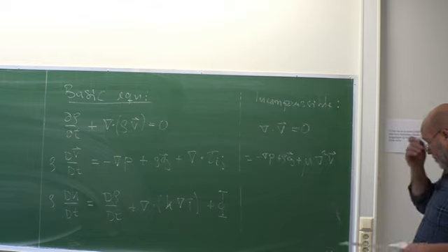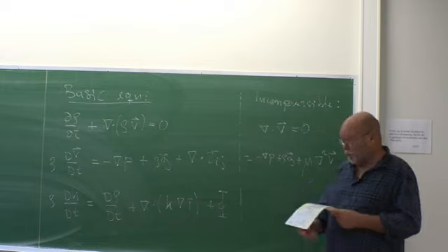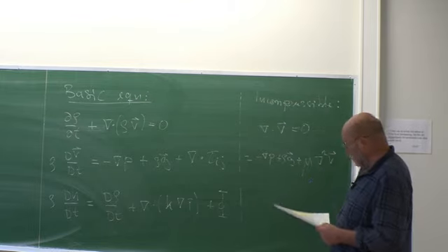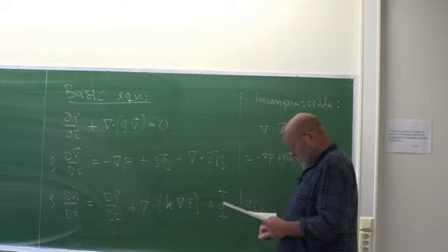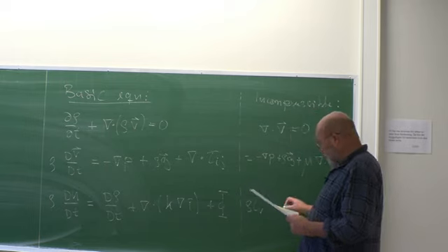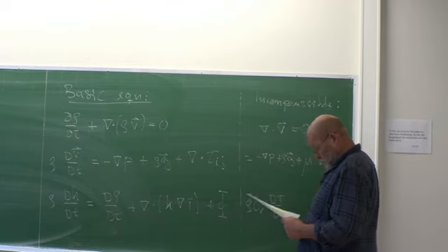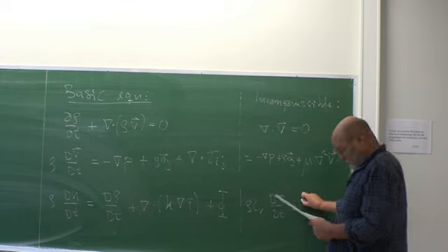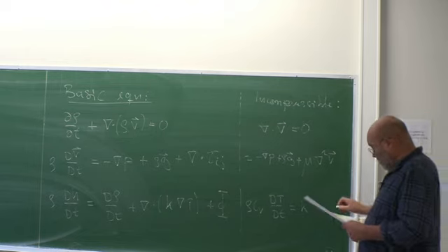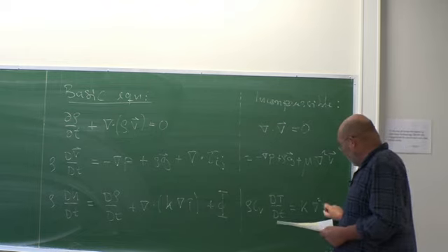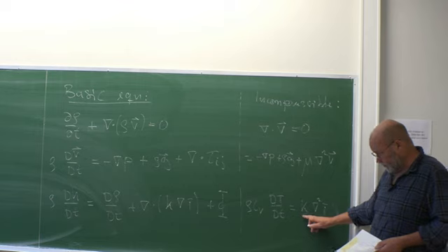And when it's incompressible, it's actually possible to make the energy equation a little bit simpler. Then it will look something like this: rho, and then you have the heat capacity there, and we're using temperature as a variable. That should then equal the thermal conductivity k multiplied with nabla squared T. Again, now all of a sudden this small k has been constant.